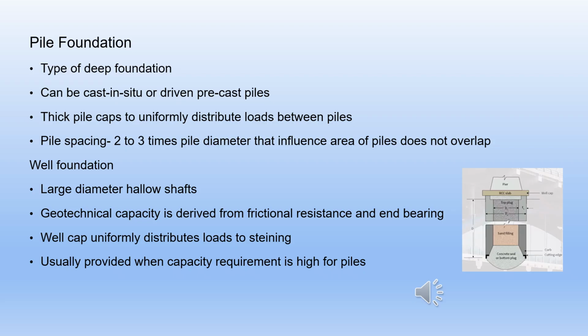Pile foundation is a type of deep foundation which usually offers high geotechnical capacity and is usually provided in groups. It is the most common type of bridge foundation, as the loads coming from the substructure are usually high. The piles could derive their bearing capacity from end bearing or friction or a combination of both. Piles are usually bored cast in situ or driven precast piles.